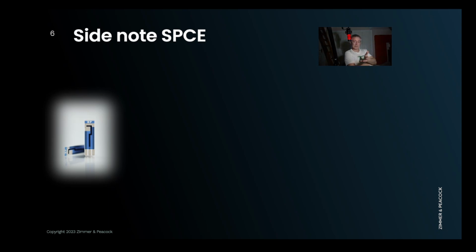There are always chemistries where you can, instead of using gold, use carbon/graphite. If you're using platinum, often people have peroxide type assays, or they may be using oxidase enzymes, and hydroperoxide is the end material of that. You can avoid platinum. You can use a mediator. You can put a mediator down on the carbon, and the mediator will then allow the hydroperoxide to interact with the carbon electrode. So there are always ways. If you're not sure of this, then it's probably worth contacting ZP.